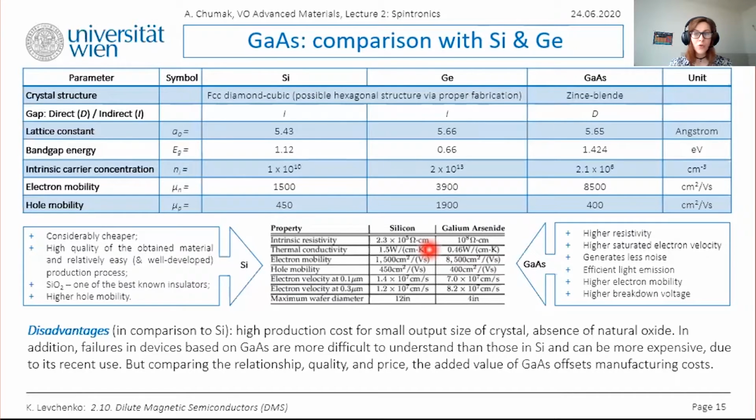It's commonly found in Wi-Fi routers, and you may certainly find gallium arsenide at the heart of your cell phone's receiver and transmitter. Another advantage of gallium arsenide is that it has a direct band gap in comparison to the indirect band gap of silicon, which opens the path to applications in optics, as well as from the point of view of electronics. It allows for the direct on-chip generation of light for signaling and detection, which would effectively allow for all-optical buses instead of the complicated design of the metal lines.